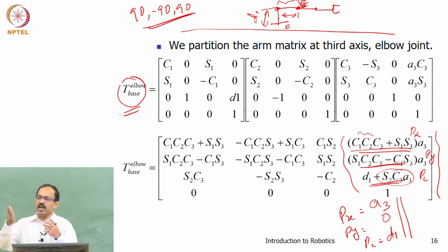Then this is different, you need to have a different formulation for doing that. But this is the standard formulation that you can use to get the DH parameters. If you say that my joint axis is not along z, then no more this formulation is valid. Then you need to have a different way of approaching it. That is complex. That's why a standard formulation has been made.